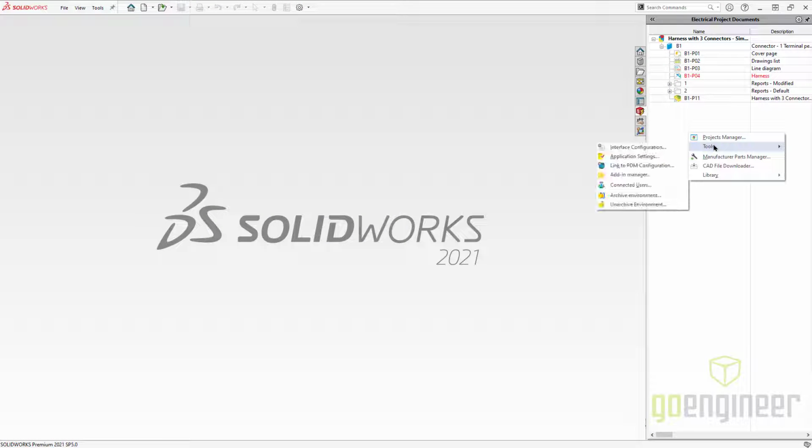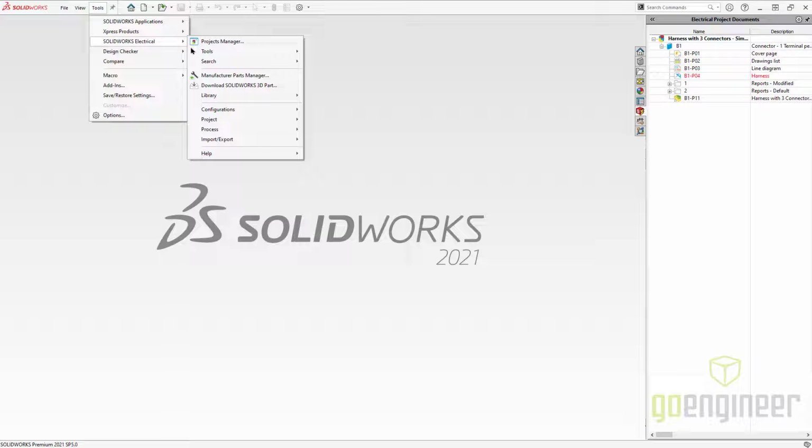Two ways of getting into your application settings. One is right-click in the blank area on the right there, Application Settings, or I can also go Tools, SOLIDWORKS Electrical, Tools, Application Settings. So this is machine specific, and if you have electrical schematics and electrical 3D on the same machine, it's the same interface.